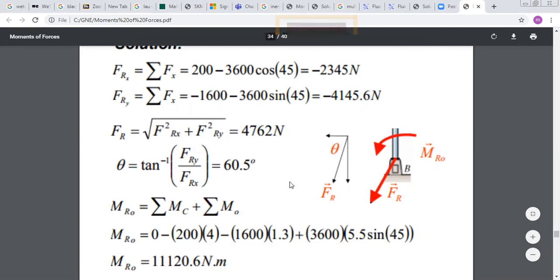In this way, you completely define your resultant force. The second step is to find your resulting couple. As you can see, they choose the positive direction as we did, counterclockwise. When you did the summation, you obtained a positive number, so your resultant couple is counterclockwise. And now you reduce your system to one force and one couple at point B.